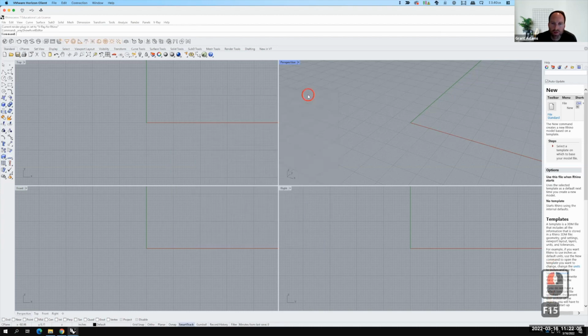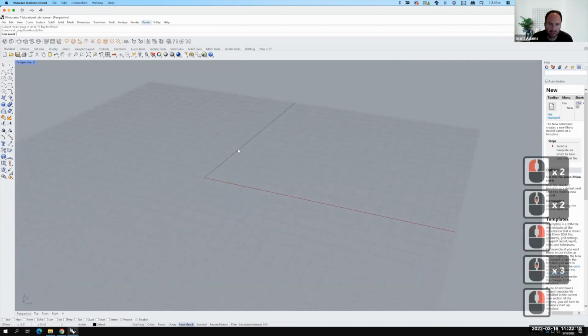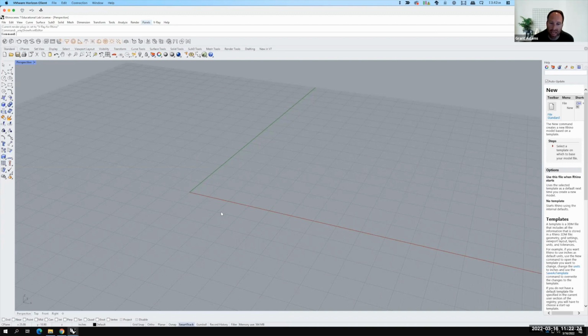Okay, so our job first off is to start to create form, or to play with form, for this skyscraper. And we can do this in a variety of ways. We can use control curves and loft them together. We can actually use what's called a cage edit to warp or twist the building in some way. So I'm going to show you those methods, and I'm going to end up creating 5 or 6 different pieces just so you can see how they come together.